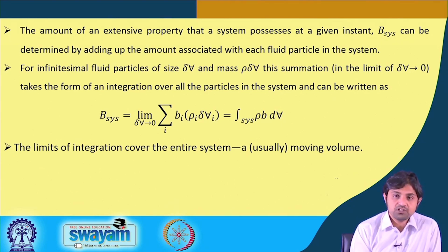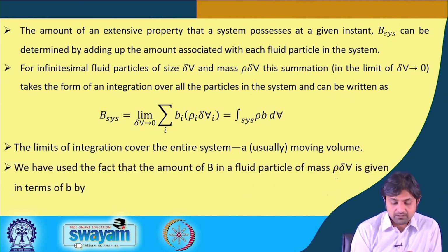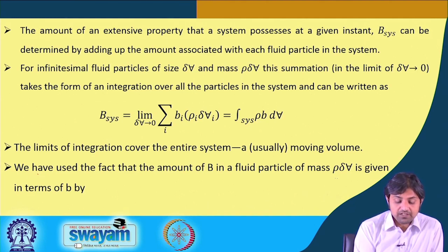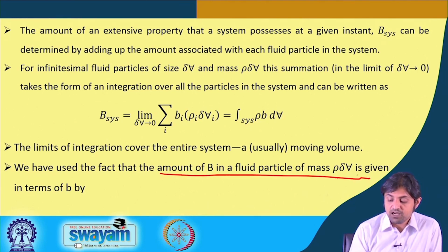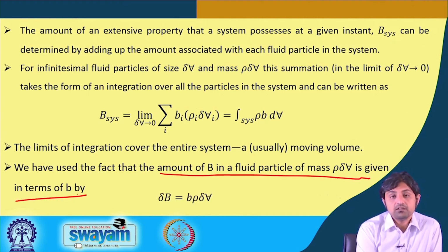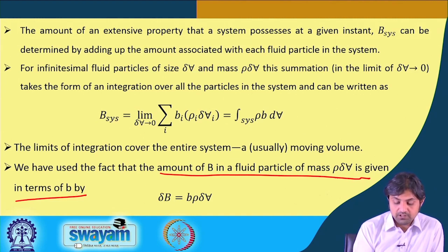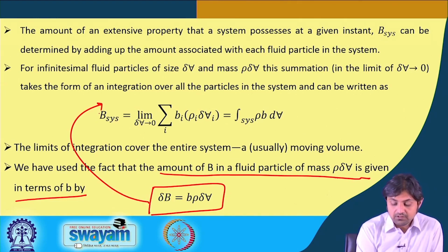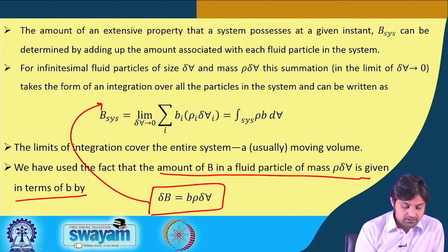So, Reynolds transport theorem is very important in that aspect. For doing that, we have used the fact that the amount of B in a fluid particle of mass rho delta V is given in terms of b by delta B equal to b rho delta V, alright.